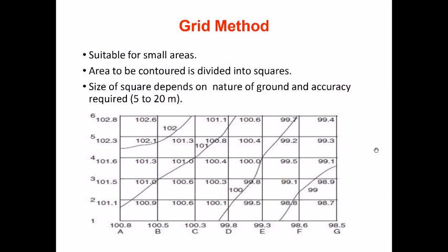So once you have chosen these values, then it depends on you to trace out on the entire map where that value could be. So let's say I'm trying to draw a contour for 102. Let's start from here. Now, if you look at these, over here the value is 98.6, over here it is 98.8. That means no value between them will be 102.